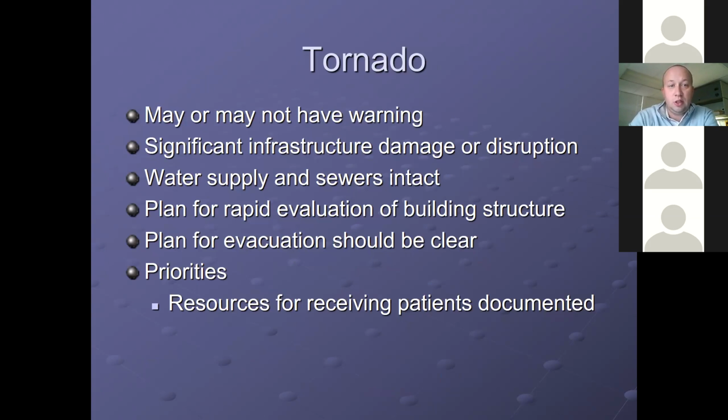So just be sure that you understand these types of hazards and what these hazards can bring, i.e. power outages, and look at your own institution. If you lose your cooling towers, what does that mean for air handling units? Does that impact your ability to hold positive or negative pressure? What about humidity? What are the impacts to sterile storage? Things of that nature. That's what we're really looking at from that point of view.